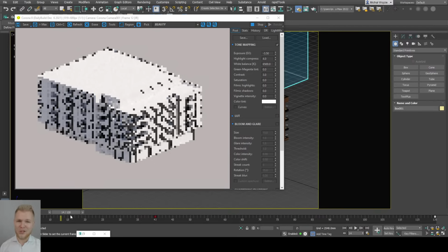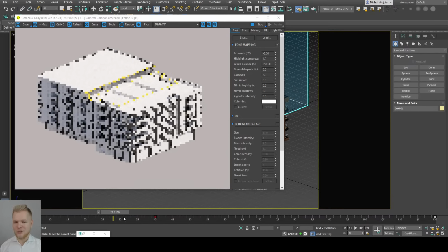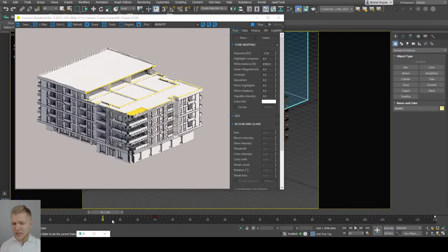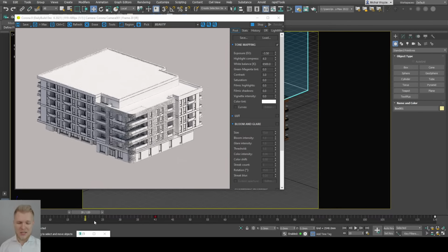Please notice that we are basically rendering this animation real time. So our cut really starts at frame number 20. So we're wasting almost 20 frames. In this case, it might be really helpful to change the 0 position of our box into something different. So we're going to make sure that we do that as well.